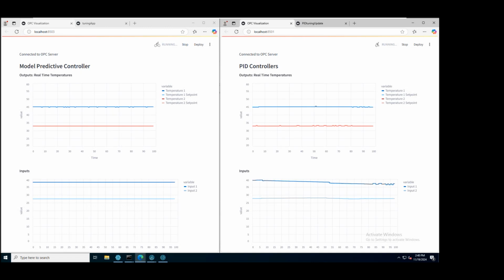And it has a few elements which make it quite a bit different to PID control, or proportional integral derivative control, which is, of course, the most widely used and most popular form of closed-loop control in industry today. So first and foremost, model predictive control is a multivariable control technology, with emphasis on the multivariable part, meaning that multiple input variables and multiple output variables are manipulated at the same time. So we manipulate a large set of input variables to control a large set of output variables instead of segmenting them into single PID loops and associating one-to-one, right?